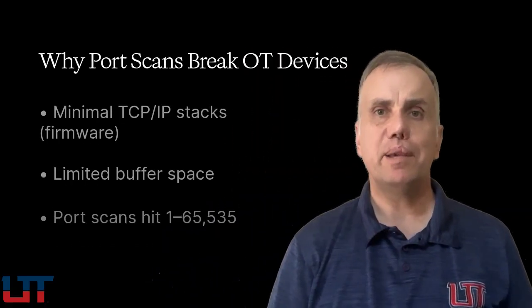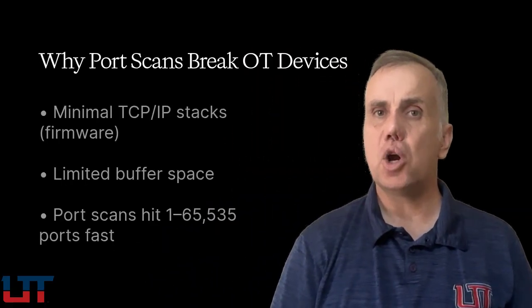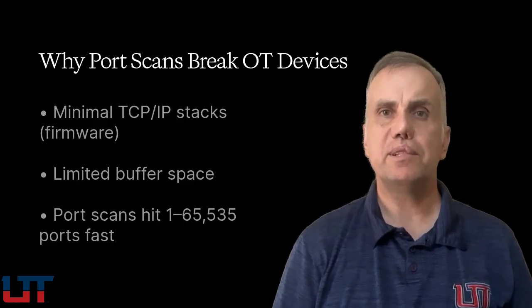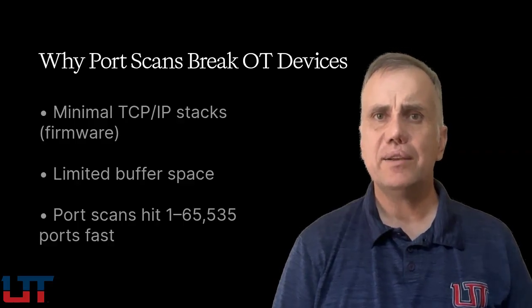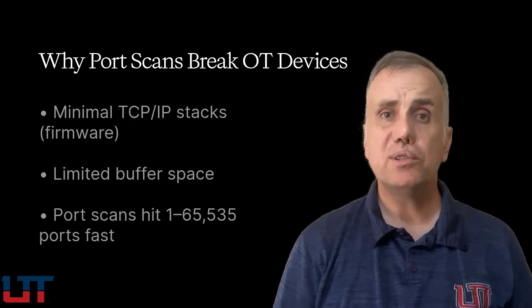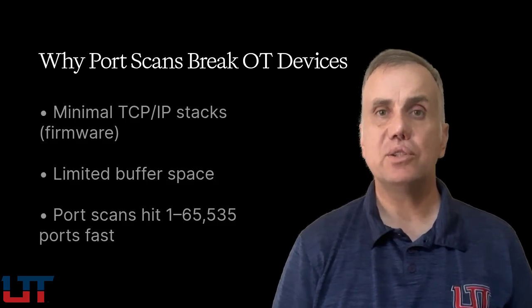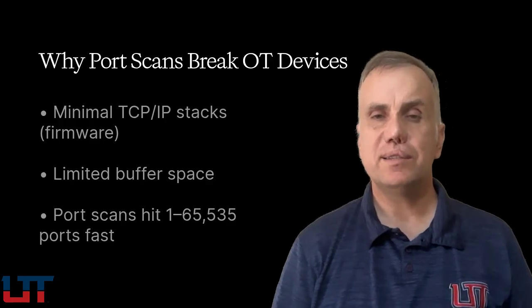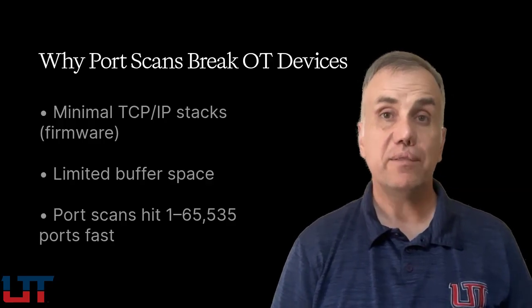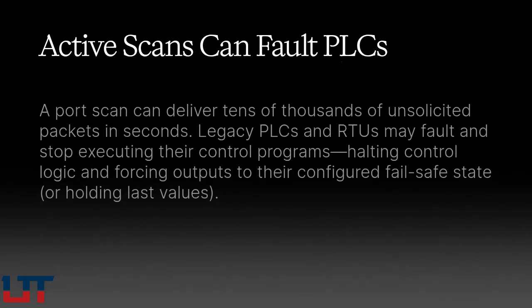The TCP/IP stacks in PLCs and RTUs are very minimal, implemented in firmware with limited buffer space, designed to handle only the specific protocol traffic they were built for. A port scan works by sending packets to every port from 1 to 65,535 in rapid succession, looking for responses. That's tens of thousands of unsolicited packets arriving at a device in a few seconds.